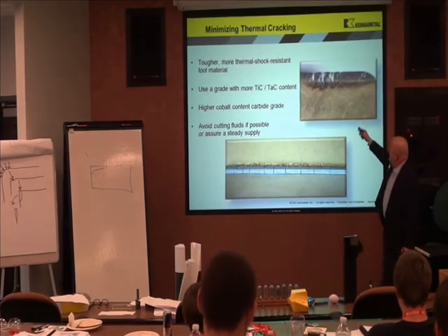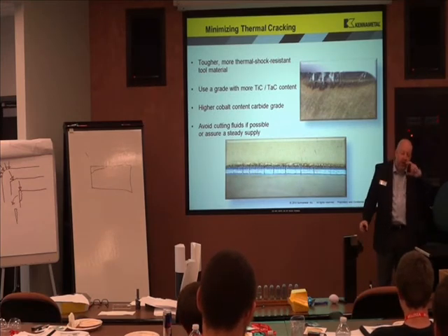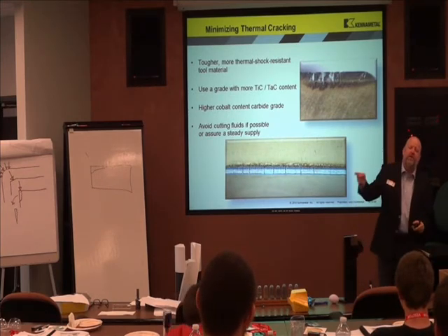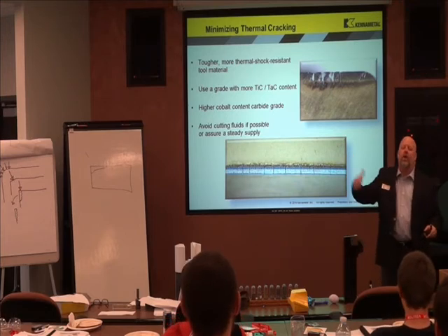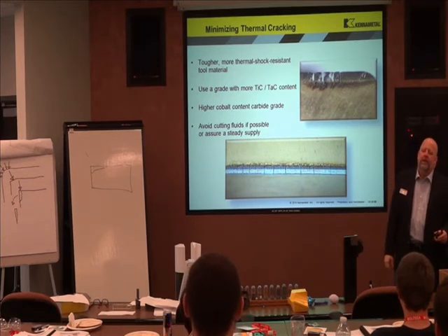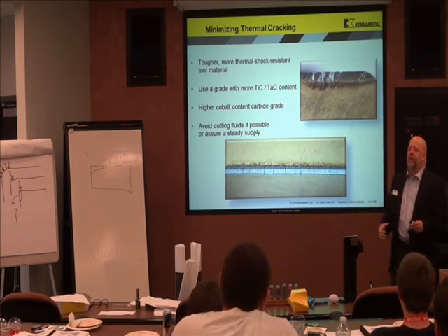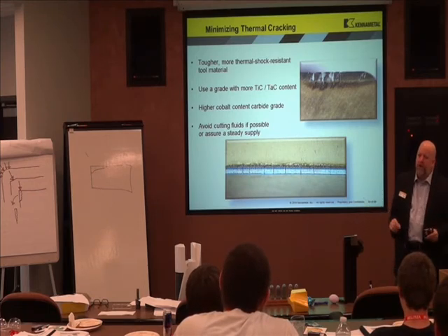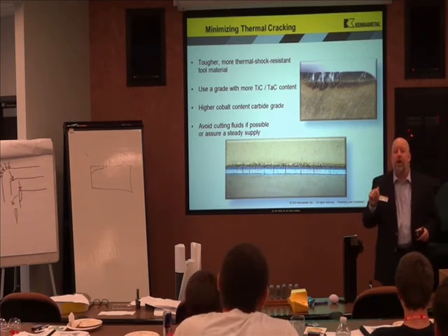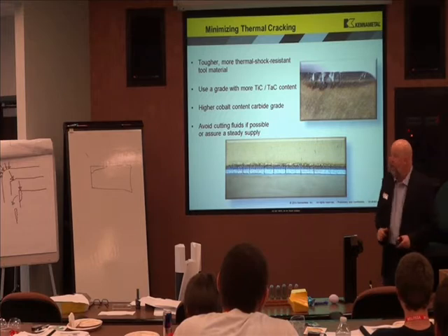So, if I'm getting this thermal cracking, if it's in turning or milling, if it's in turning and I have an interrupted cut, turn off the coolant. If it's in milling, turn off the coolant. If I can't turn off the coolant, I need a tougher grade of carbide, which means it has more cobalt.